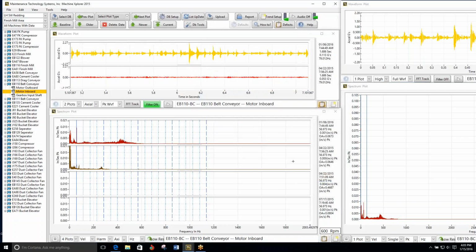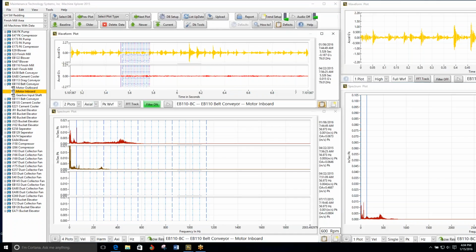So I hit save here. So if I do that, stretch this guy out to where it hits the peak here, something like that. Tells me it's about 15 hertz is the frequency there. How many hertz does the shaft turn? Good question.